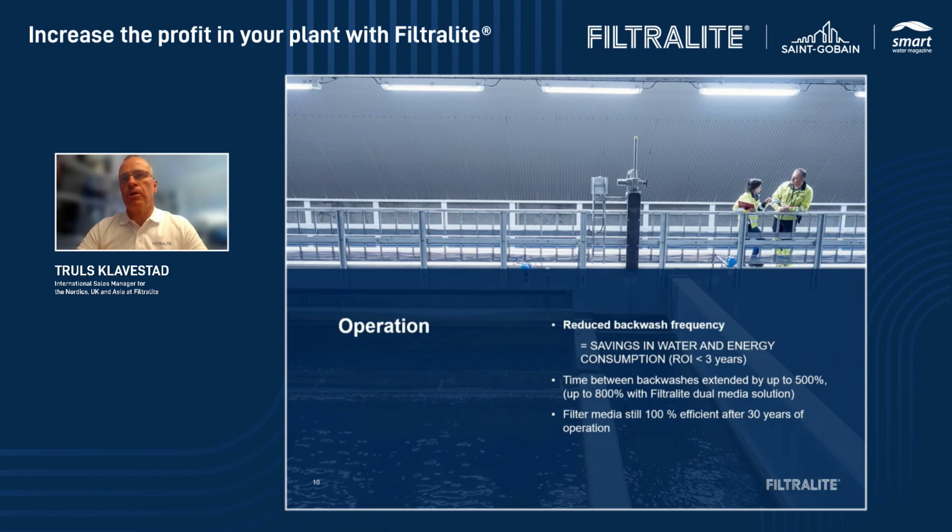So less backwash will give a saving in backwash water, and when you use less water for backwashing, that means you have more water available to sell to the client or out to the municipality. And less backwash also means less use of energy. So if you take these two together, the saving in water and energy, you always have a payback time, always less than 3 years.